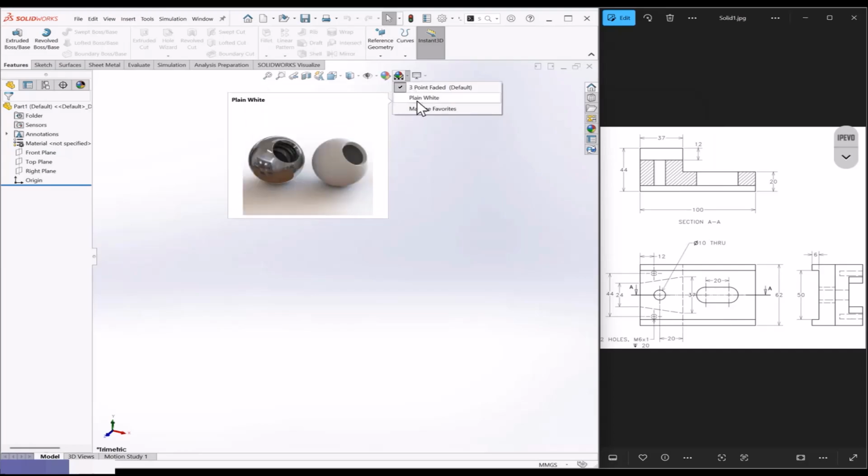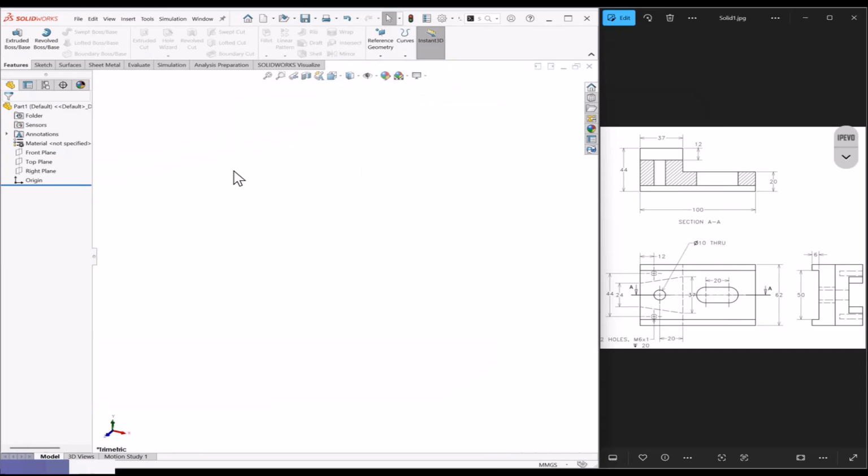I'll set to white plane. Now which plane will I take? I'm going to take the right plane. I'll draw from the sectional view because from this view, I can understand the shape is a step. It's forming a step shape. But if I see this view, I am confused, it looks like only a rectangle. But I can see there are some material cuts, like a hole and a slot. So it is not exactly a rectangle when we compare to the section. Okay, so we'll go to the section, then add the depth, and then cut the material which is not present in the part.